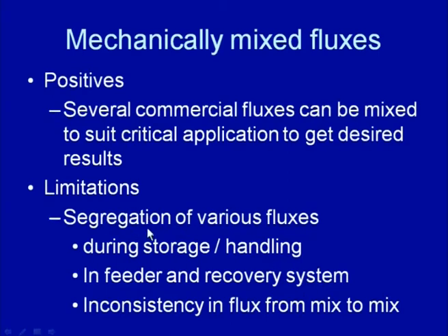So, the segregation tendency during storage and handling, or also in the feeder and recovery system, leads to variation in the composition of the fluxes, which can lead to variation in the performance of the fluxes during the welding. Even since these are made by mechanical mixing, inconsistency can be there from mix to mix in the composition and the performance of these fluxes during the welding.